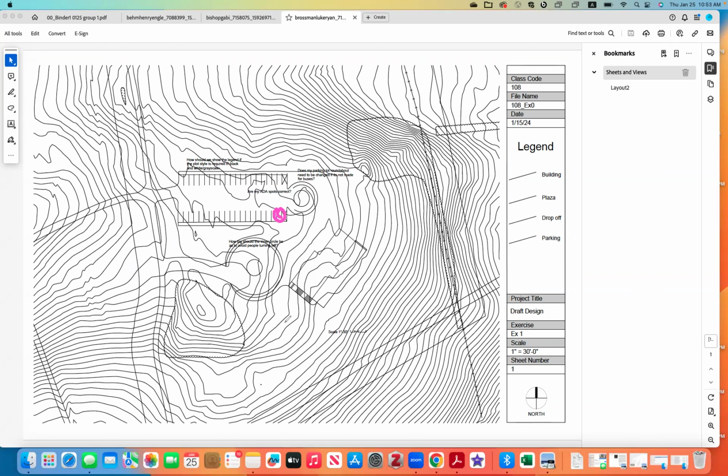Your parking lot roundabout need to be changed. I don't know if you have enough. No, the radius, it's correct. I would suggest that you check the grading class final project. That turnaround example given to you should be a good example to follow.